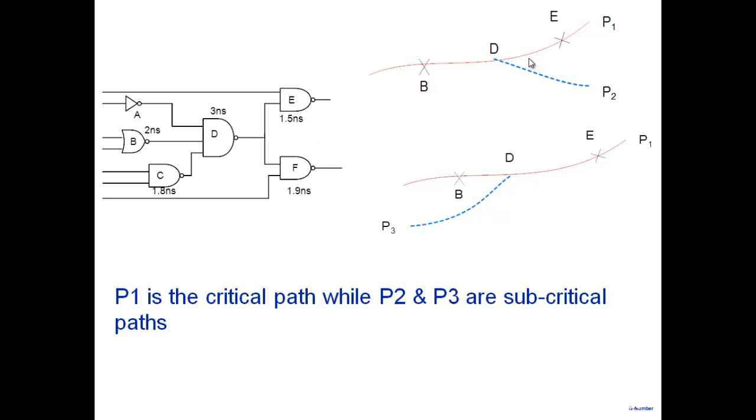So the idea is in the simplest possible manner to tell you how this static timing analysis is carried out. The tools that are actually there, they may be doing things much more efficiently, but at the heart of all of this is that the circuit is transformed into a graph. Things like maximum arrival times, maximum delay to T, these are the concepts that are played with, and one arrives at the different paths that are there in your circuit here.